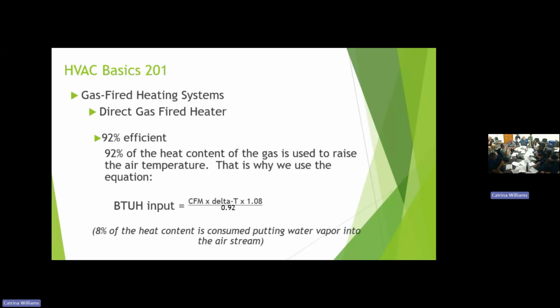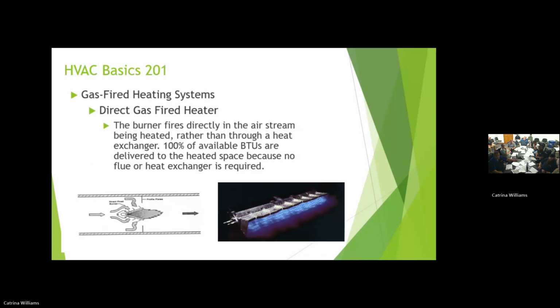Okay, so that's at the actual controls is where that would be? It's on the unit there, right? The air switches are right on the burner profile. Back up a second here. You'll have a couple tubes sticking through this that measure airflow, one set for high pressure, one set for low pressure. Either one of those trips will shut it down. And the high temperature switch is typically mounted right in the discharge of the blower.